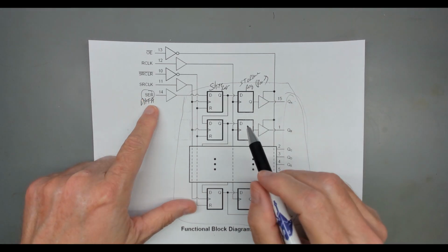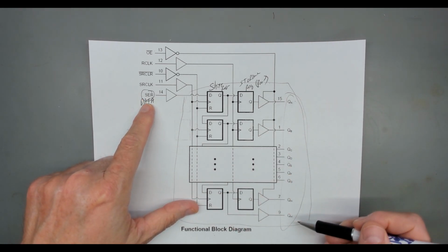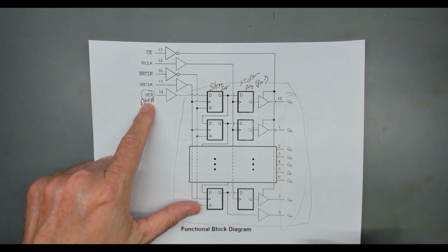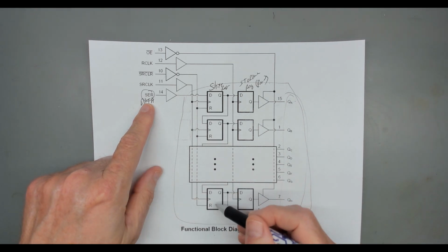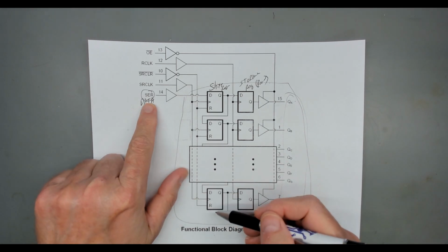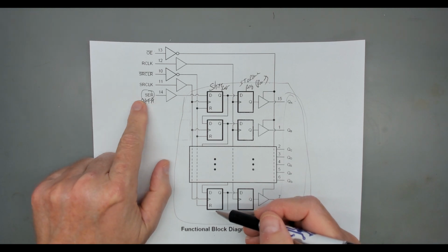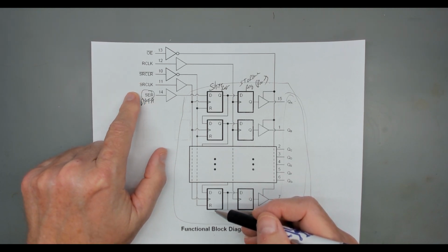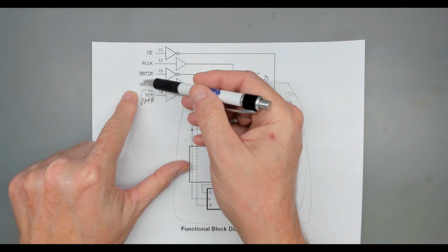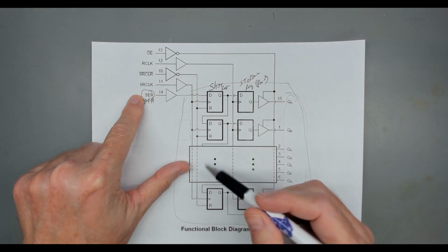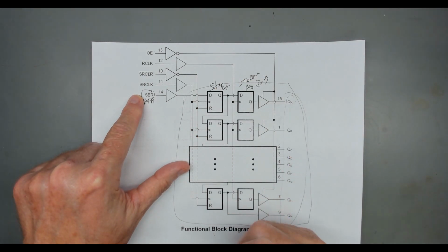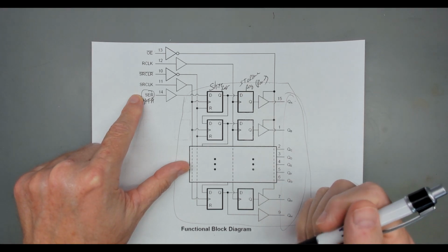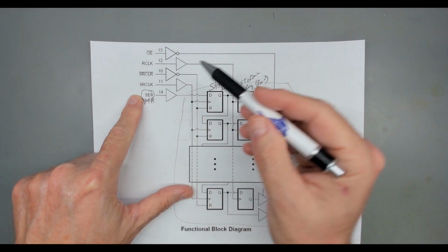That's your registers. Whatever you want, if you're working with this single chip, whatever you want into H, this one, the very last one, you put it here. If you want a 1, you put your high, you turn your voltage on, you put your high up, and then in your shift register clock, you cycle high to low. You go up and then down, 1 clock cycle. When you do that, this data gets put in here.